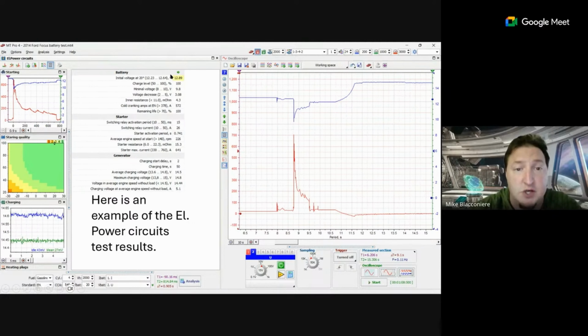You can see it generates a bunch of different information based on the oscilloscope measurements. And this is what I captured on the oscilloscope. You can see it's about a minute long. The whole process includes switching the loads on and off, running it at a higher RPM, and then also switching the loads on and off. But it'll show you your charging voltages, your averages, and the ripple.